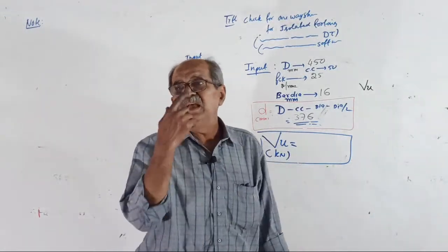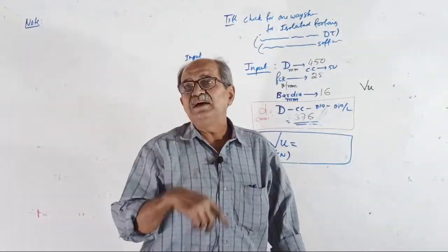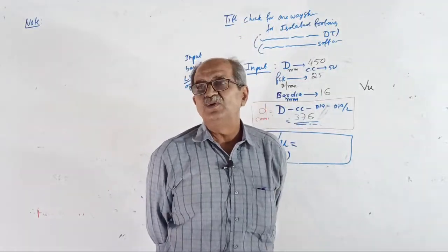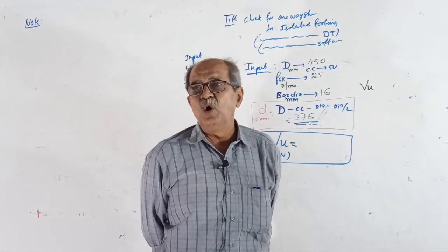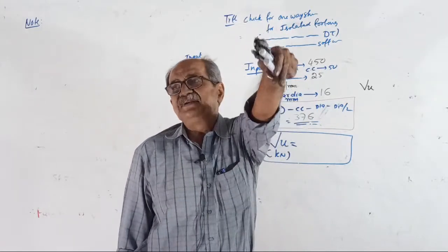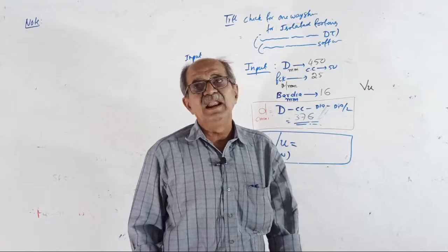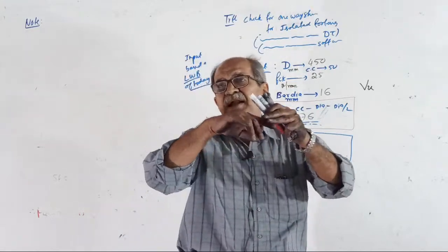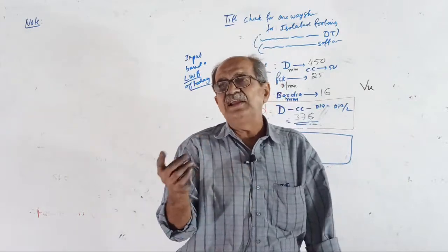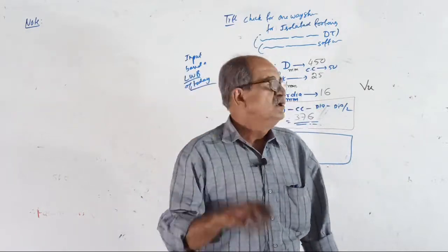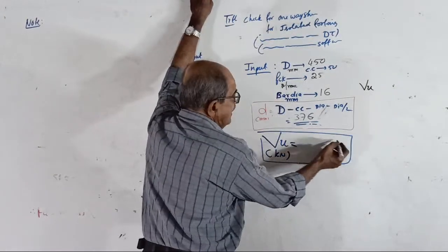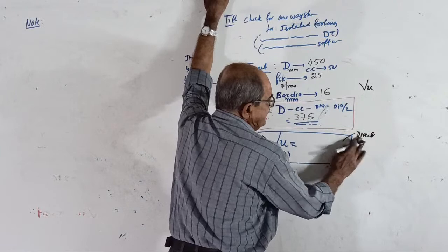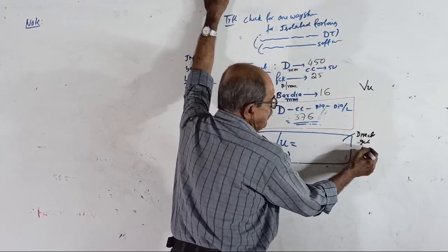But one thing, you should activate the factored value there, not the working load value. When you go to the result sheet, you should go for the factored value. Clear? Among the different combinations, you can also ask it to give the worst value. So this is how you directly take it from the software.